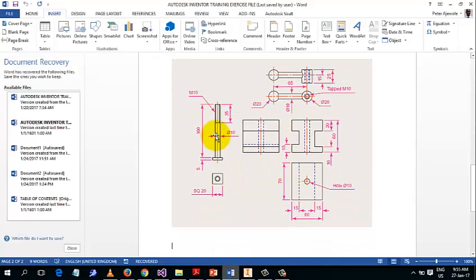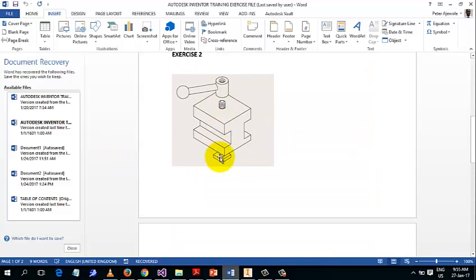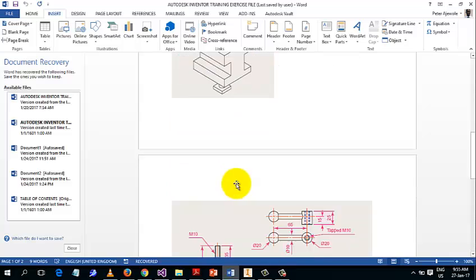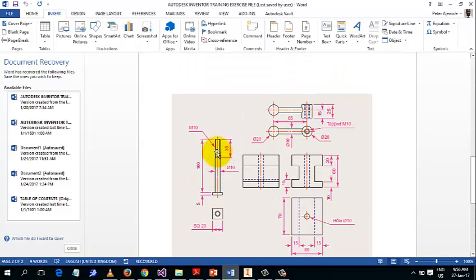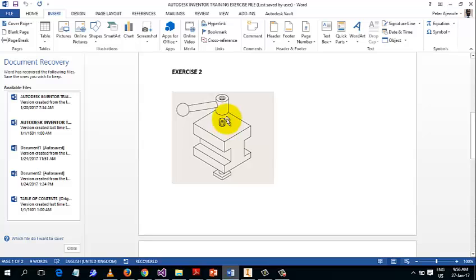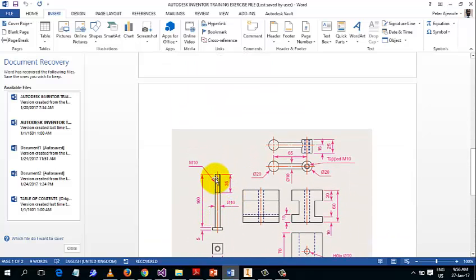So that is that component there. We are through with that component. Then the last one, we need to work on this last one. Now this last one consists of a long bolt with a rectangular head or square head. Let's see whether it is rectangular or square. That is a square, square 20, SQ there. It's equal to a square head. And it also has a threading on top, but the threading does not run through. You can see that the threading is only at height 35 and it's M10, that's diameter 10.